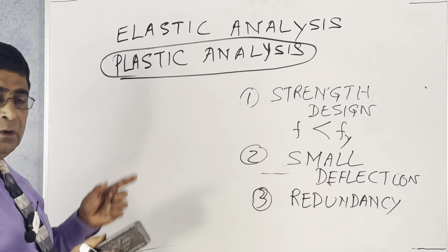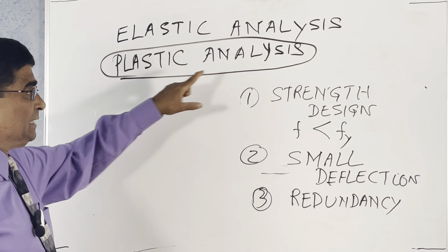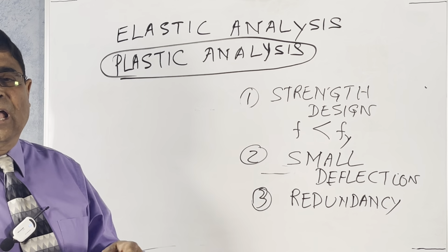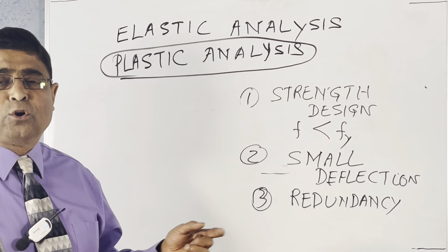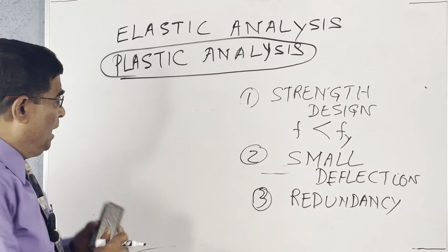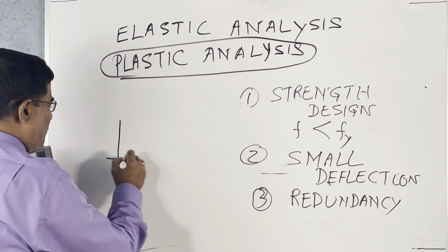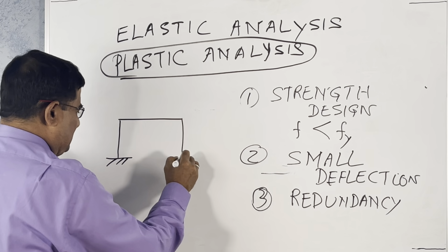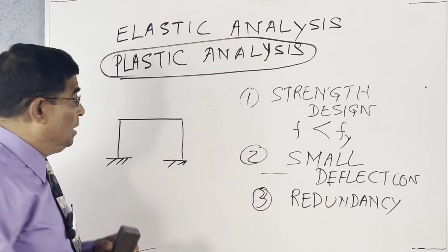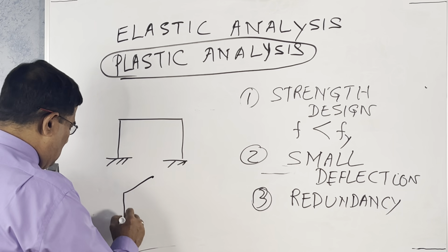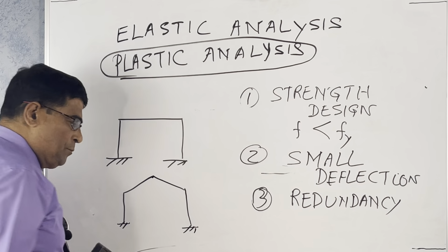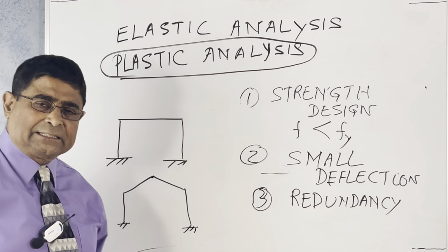But that is how we use plastic analysis, to make the structure like a determinate structure and find out the forces. So this is not much relevant nowadays. It is good for analysis of portal frames, which were usually difficult to analyze by the elastic method earlier, not now, because now we have computer methods. Or a gable frame like this. Earlier they used it mostly for this kind of structure.